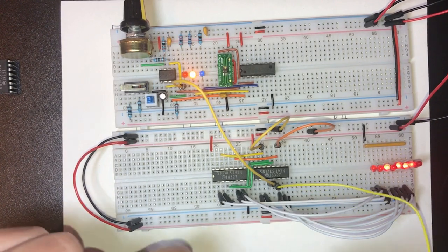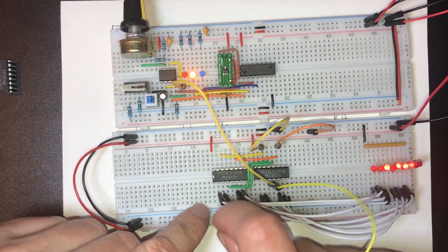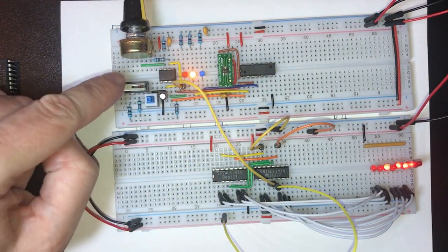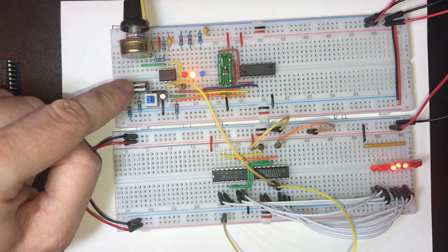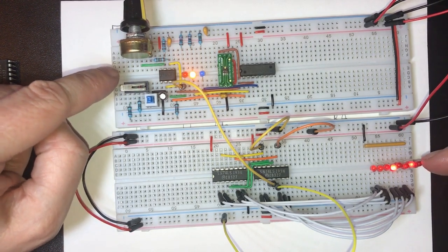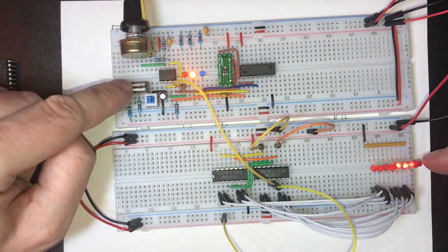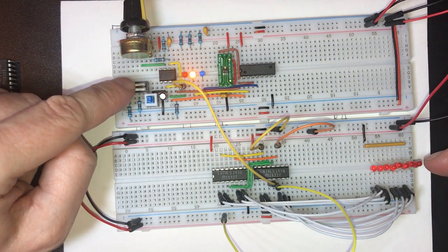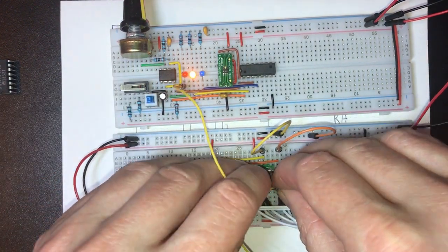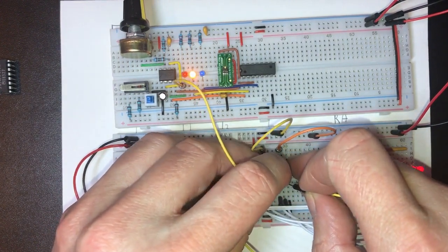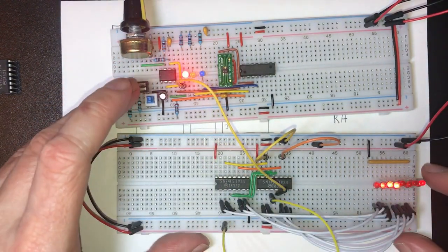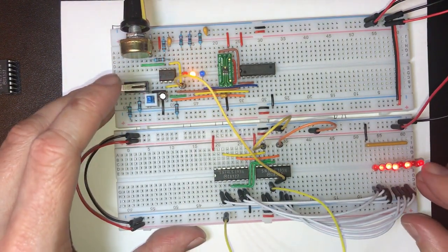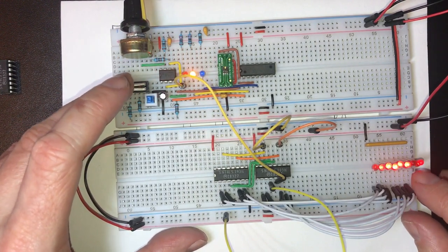So what I actually expected was that the ones I wasn't using, I would be tying down to the ground. Now, when I click here, this is completely bypassing the least significant bit, and it's giving me some odd behavior. If I swap these over, this least significant bit is always on, and it's effectively counting correctly from the next bit.